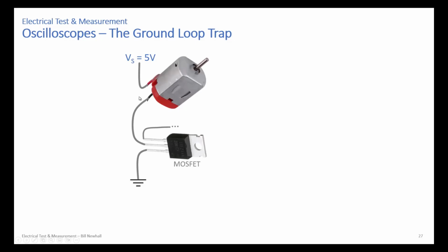Let's suppose you have a motor that is being controlled by a MOSFET, just like in your project that you're building. So you have the motor, and the MOSFET connects or disconnects the ground from the motor. You want current to flow this way down through the MOSFET when the MOSFET's turned on. All right, let's define a voltage across that MOSFET, VFET.